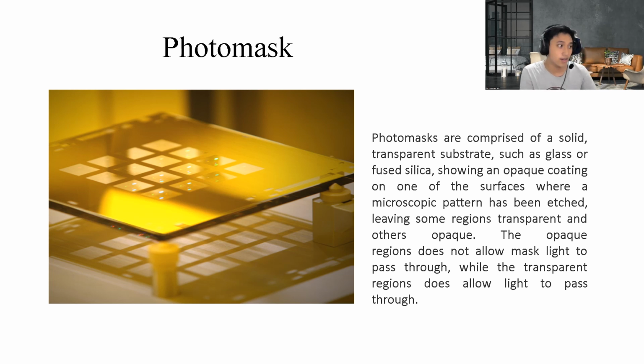The next one is photomask. Photomask is the use of light to print circuit patterns into a wafer. We can understand it as semiconductor parts drawing on the surface of the wafer. The higher the fineness of the circuit pattern, the higher the integration of the product chip, which can only be achieved through advanced photomask technology.